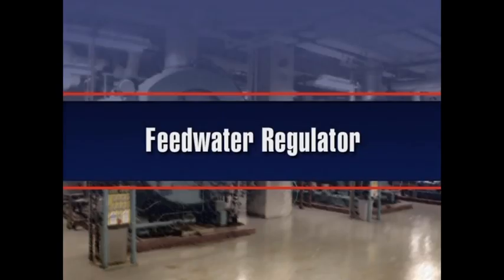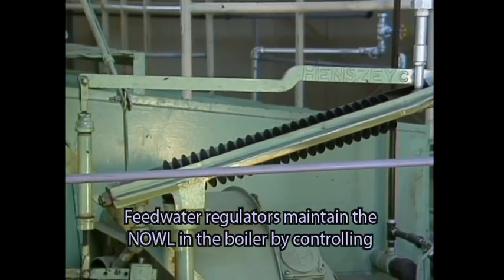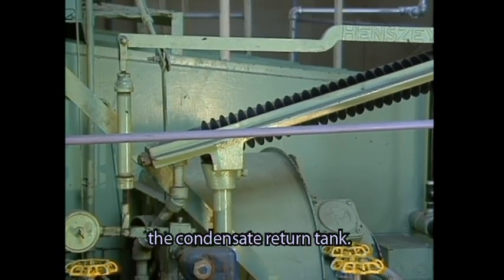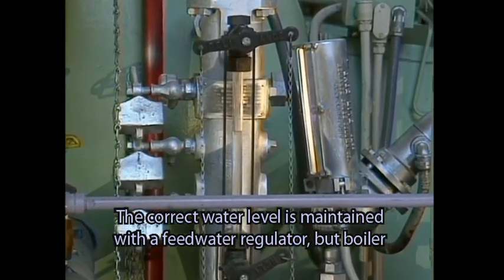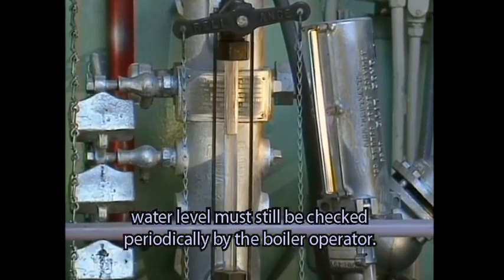Feedwater regulator. Feedwater regulators maintain the NOWL in the boiler by controlling the amount of condensate returns pumped to the boiler from the condensate return tank. The correct water level is maintained with a feedwater regulator, but boiler water level must still be checked periodically by the boiler operator.